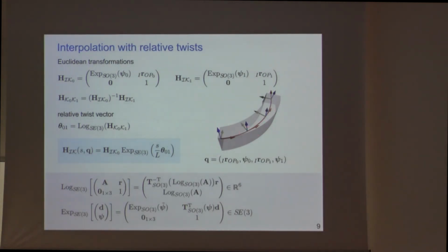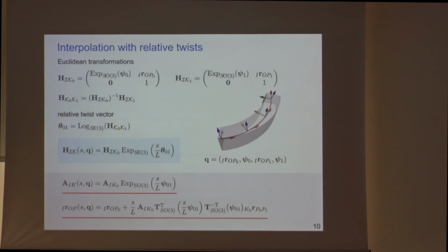And in between, it's just a highly nonlinear, coupled interpolation, and if one carries that out, for the orientations, what one sees here is the usual SO3 interpolation that one knows maybe already from Crisfield and Jelenic, who proposed that in 2001. But what is somewhat special is that in here also the center line is extremely nonlinear, and if you now think of taking the variation of that, you know that you don't want to do that.